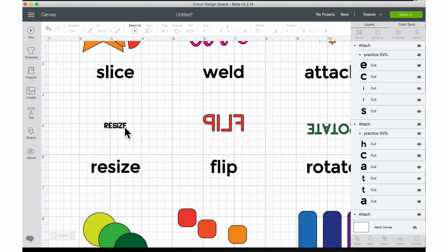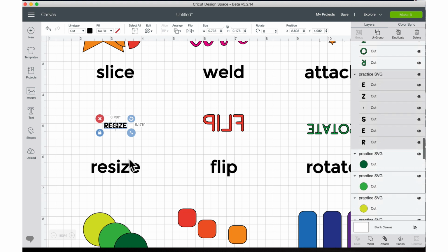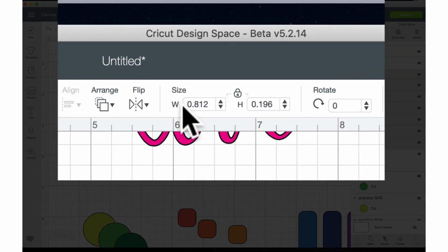And we've already covered this a little bit, but I just wanted to show you more in depth how you can resize an object. So we covered how you can resize it this way. But another way that you can resize this object is up here at the very top. This bar over here shows the measurements. It's got the width, that's what W stands for, and then it's got the height. And then it also has the little padlock, which allows you to lock or unlock the proportions.